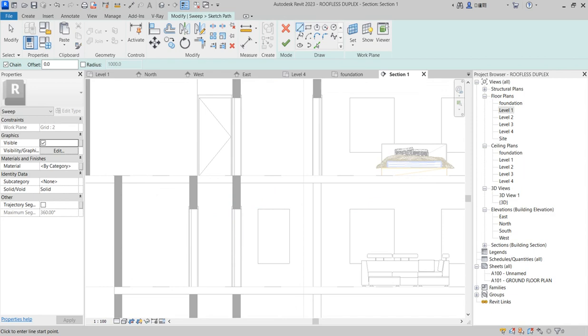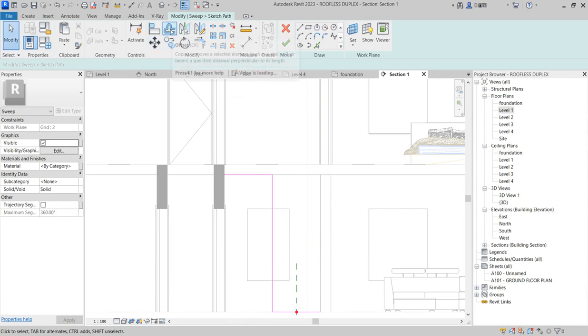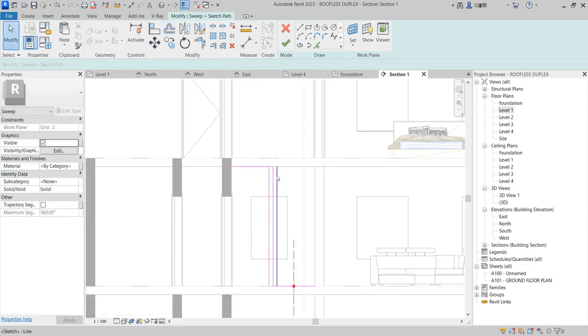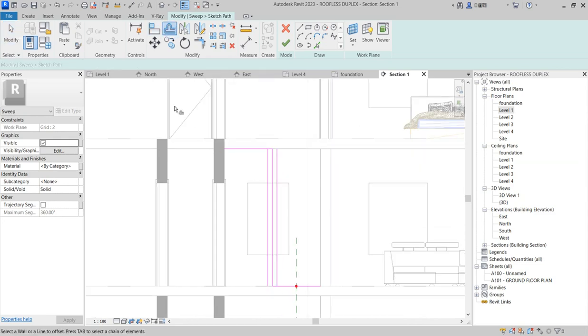The first thing I need to create is the horizontal line to the middle, and this line again to the middle. I will join these two lines together, so it's divided into 2, which is good. What I need to do next is offset this by 100 so that I get the radius aspect of that staircase accurately. I'm done with this one. Now I need to move this one again to change the starting point to 150. Move it without copy, so 150 and then 150.